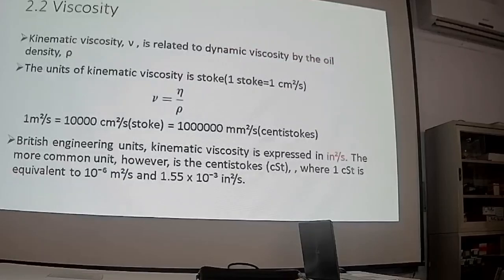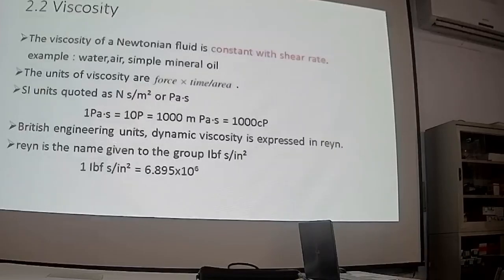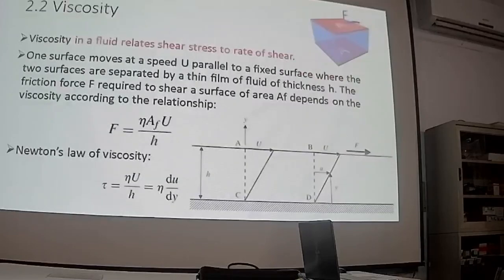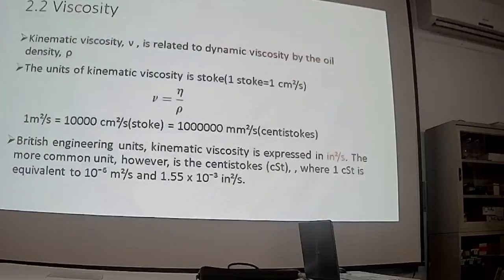We also give you the definition of kinematic viscosity. It's related to the dynamic viscosity by the oil density. The viscosity we call here is dynamic viscosity. If this is divided by the lubricant density, it is called the kinematic viscosity.